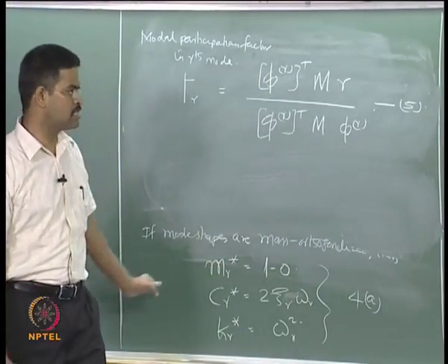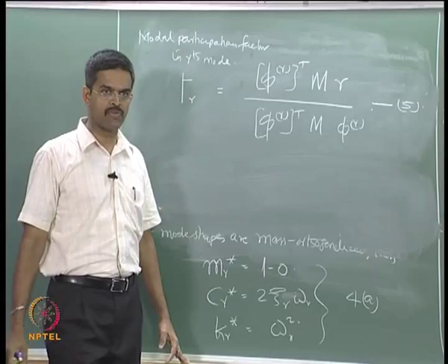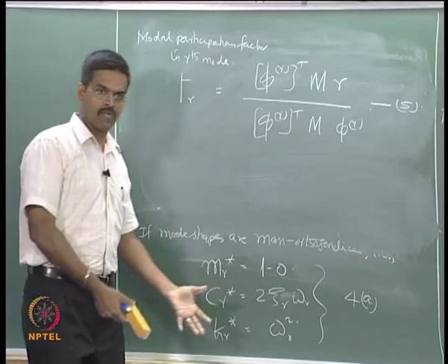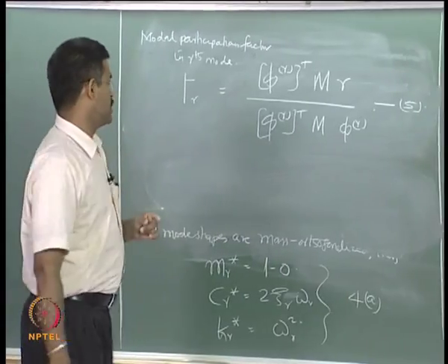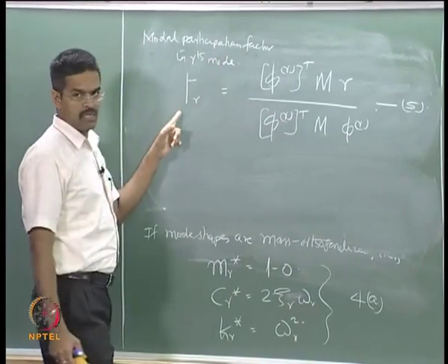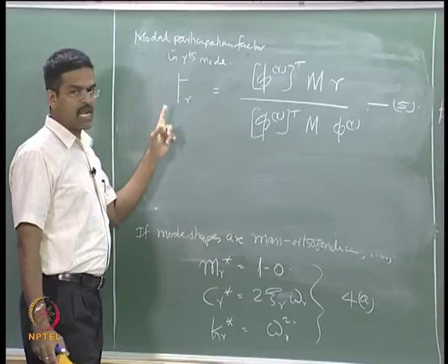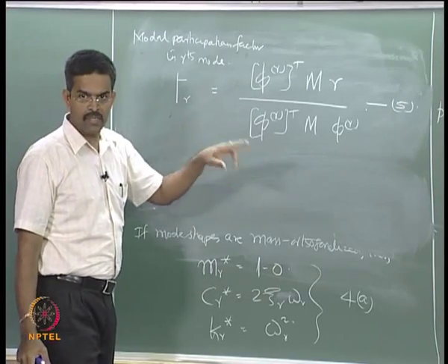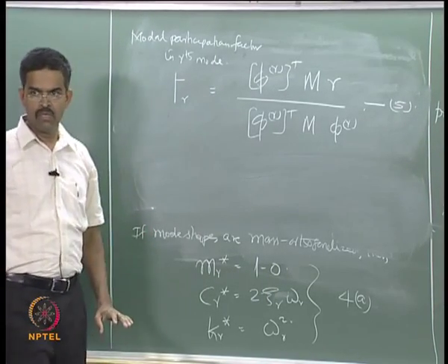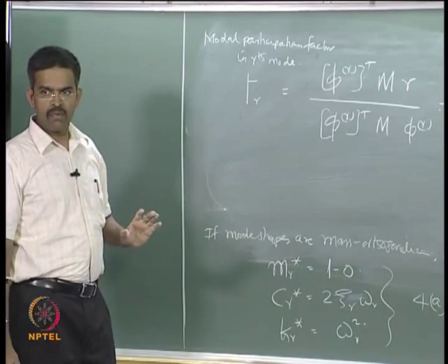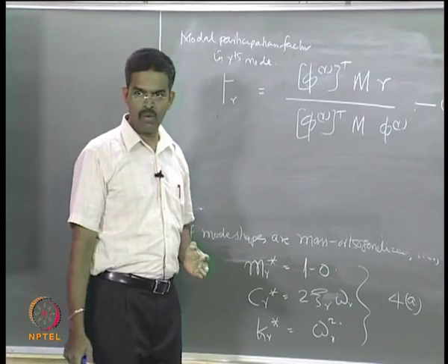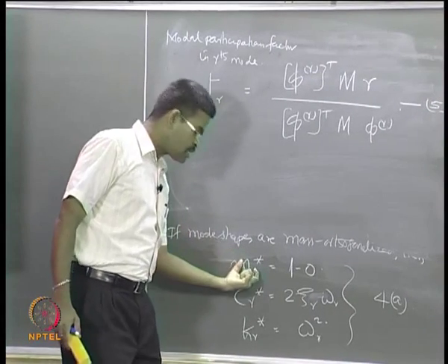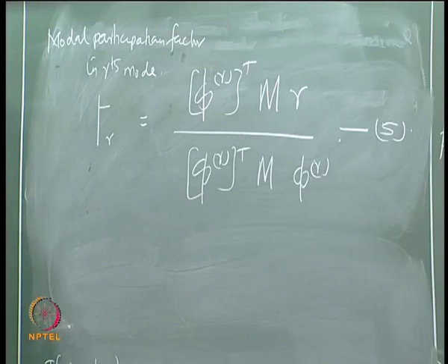If there are n degrees of freedom, I will get n mode shapes and n frequencies. Should I use all of them? There are two ways of looking at it. One, estimate the modal participation factor, use this factor on every mode shape and then get their x value. The other way is to truncate the modes depending upon the modal mass participation in the whole system.